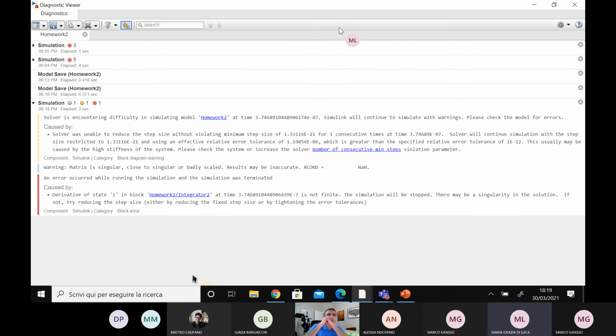Okay, something else. Ooh, I gave you the wrong suggestion. Derivative. Wow. Well, I think the solver is fine as it is. It's just that something is happening. Maybe it's because I'm violating the step size. So you have variable step ode45, max step is 0.1, relative tolerance is 10 to the minus 6?